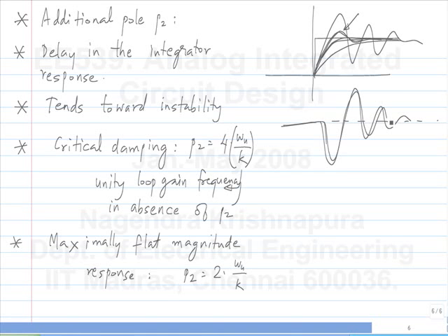Okay. So if you make a voltage regulator, the static specification will say the voltage has to be this value to this accuracy. Maybe 1.2 volts plus minus 5% or whatever the accuracy for that application is. And the dynamic specification will specify all kinds of things, like if the input voltage is changed in a certain amount of time, the output voltage should settle within a certain time. And similarly, if the load current changes, then the output should settle in a certain amount of time, etc.